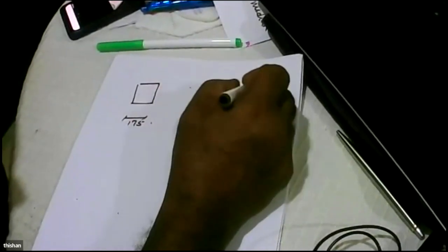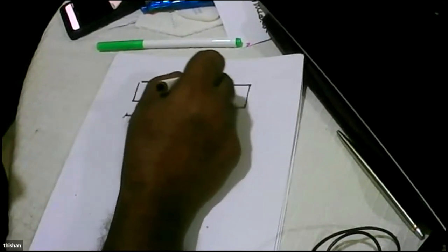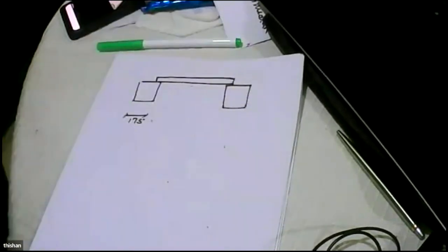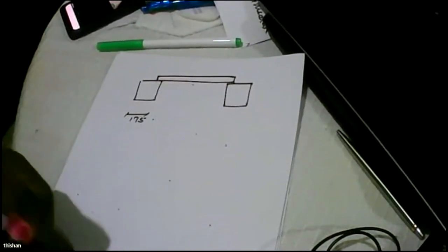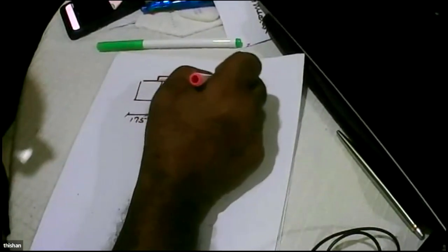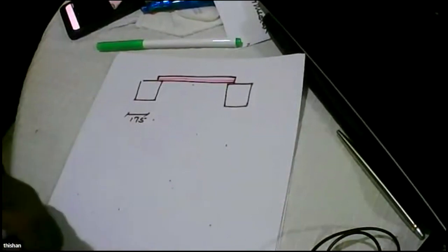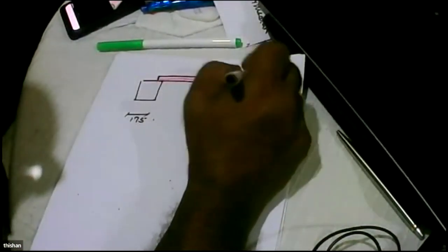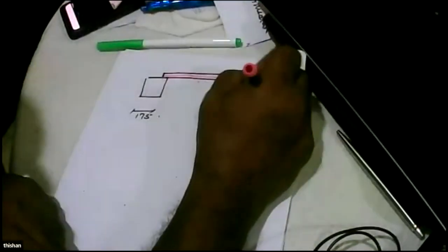And because these are small spans, a minimum bearing of 40 millimeters would be sufficient. But the important thing is, because we have only a small bearing, we make sure the reinforcement continues from here to here. We make sure the reinforcement is of full length, because we don't have a cover problem or anything, because we are going to put concrete here. So we continue the reinforcement to the very end of it.